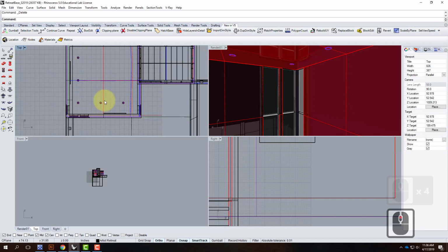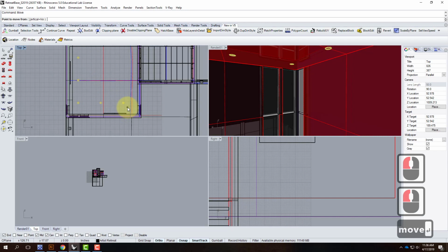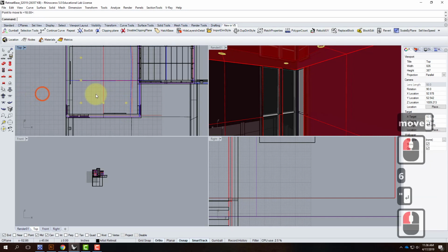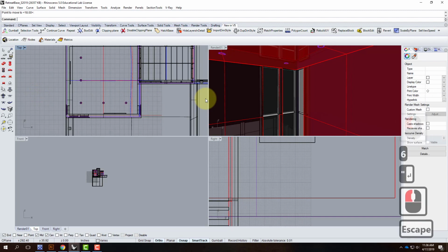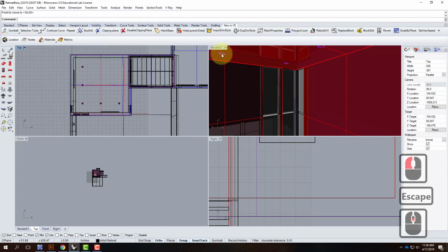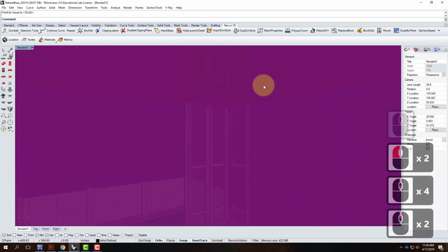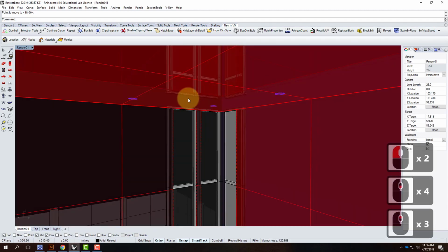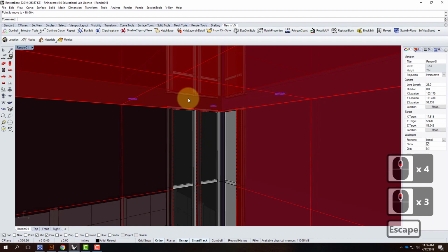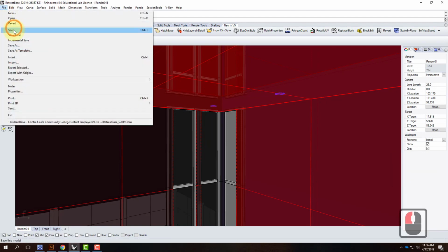Now, maybe or maybe not, this is good placement of the lights. We can adjust and move as necessary. It's bugging me that they're a little bit off, so let me move these over by about 6 inches. And that feels a little bit better. So I've created them. They're in the perspective view now. That's good. Remember, I can't create the V-Ray lights here because they won't come through in the block. So we'll go ahead and just save this.